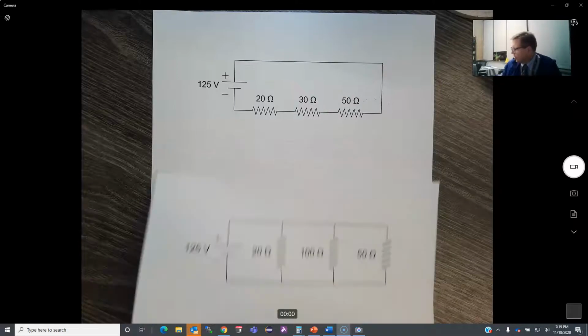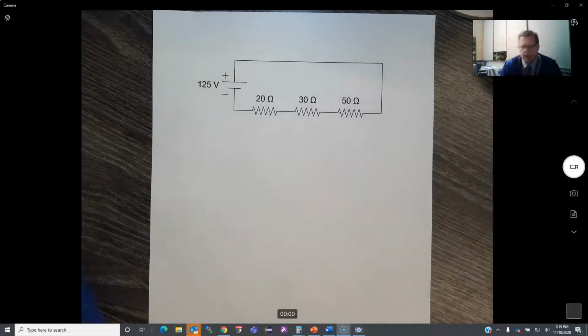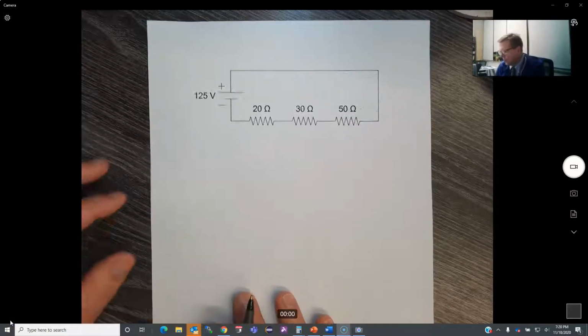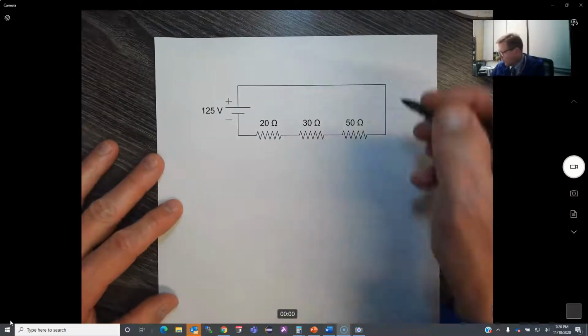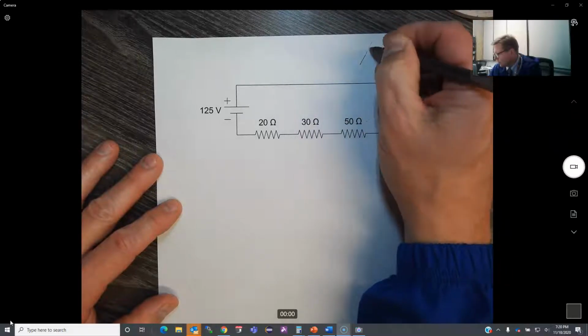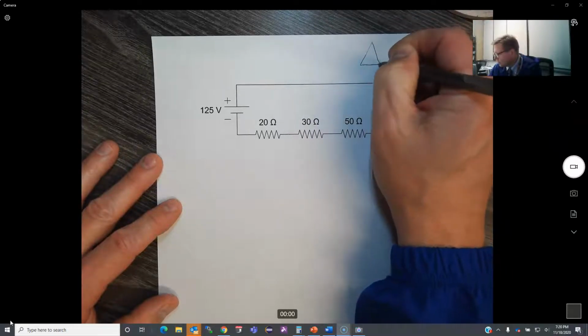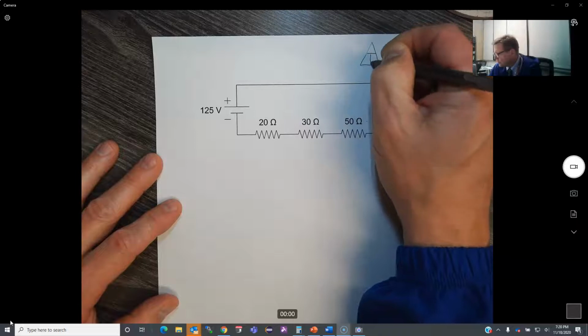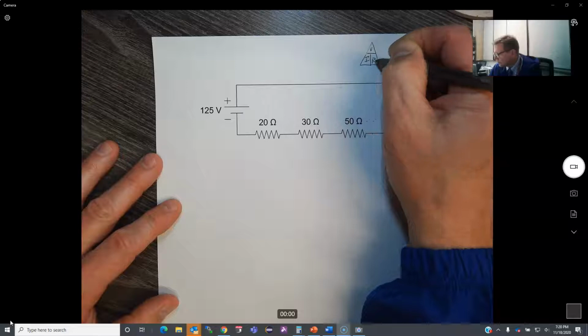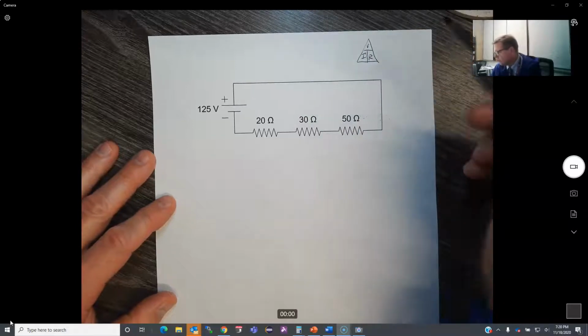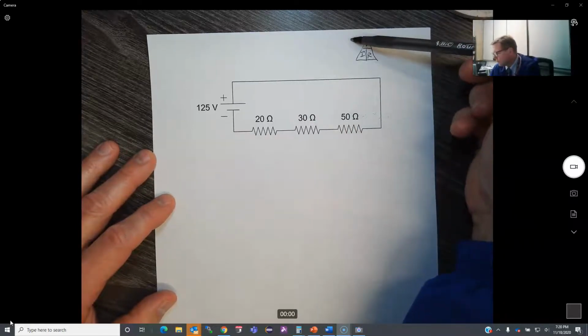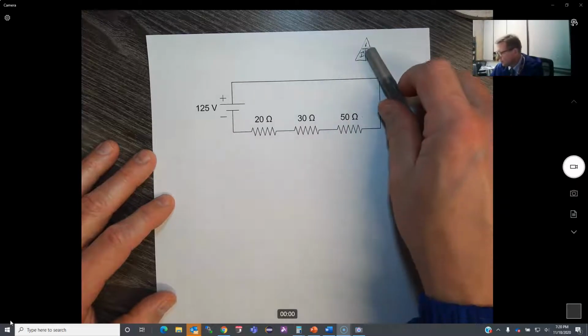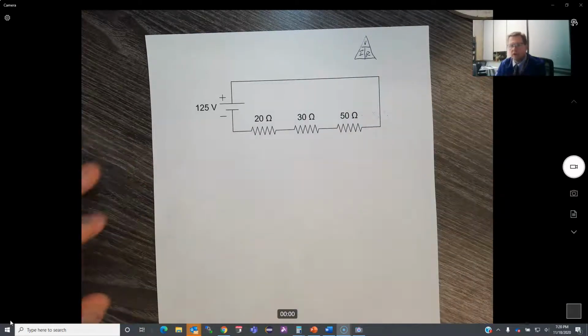So what I'm going to do is start out with the series circuit first here. We're going to go ahead and work on that one. So let's talk about, remember, we have Ohm's law involved here. Ohm's law is just V equals IR, or the quick, easy way to write this out: let's draw the triangle with the T inside of it. This is V at the top. We have I right here, and R is my resistance, right? So at any time, if I cover up the V, then it just says I got to do I times R. If I cover up the R, it says I got to do V divided by I, and so forth on down the line. All right, so that's my Ohm's law that I have.